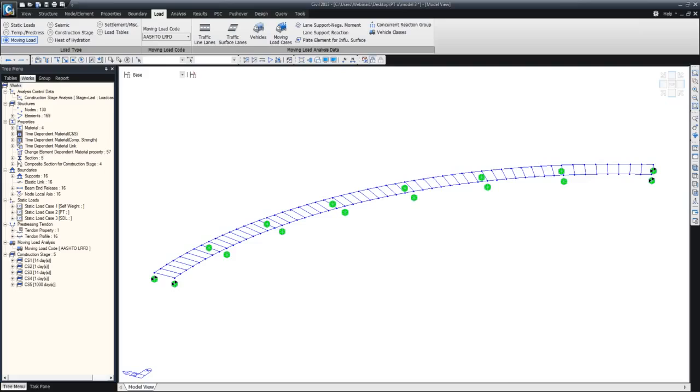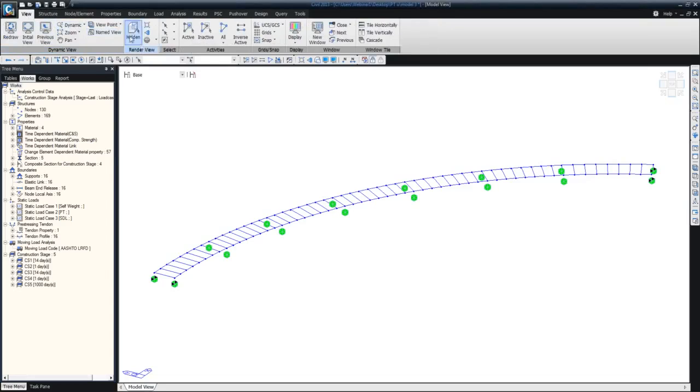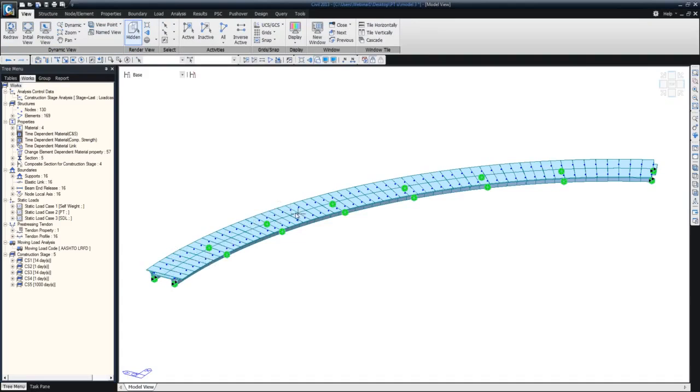We call it a dummy element because it is not really in the physical world that you can see. It is just to replicate the transverse stiffness of the deck. So when we are saying we have the lid slab and the deck slab in the picture, we are saying that their longitudinal stiffness is taken care of, and the transverse stiffness of the deck is being represented by a transverse member.